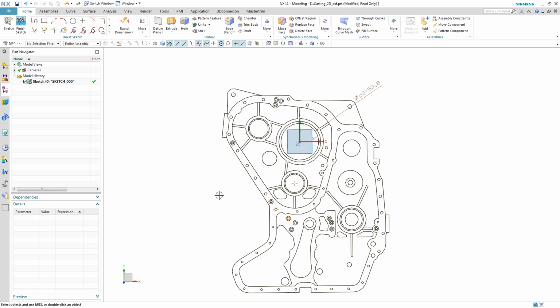Sometimes you're not paying attention when you're drawing, you just want to get the geometry laid out there, and then you realize that you made it double the size it's supposed to be. You put that first dimension on there, and all of a sudden, maybe it's some odd shape, you don't get the reaction you thought you'd get. The line gets real short, but your holes are now outside instead of being inside the part because there was no associativity, or you didn't put any dimensions on that prior to it. So this allows you to scale that whole entire drawing, which makes it a lot easier.